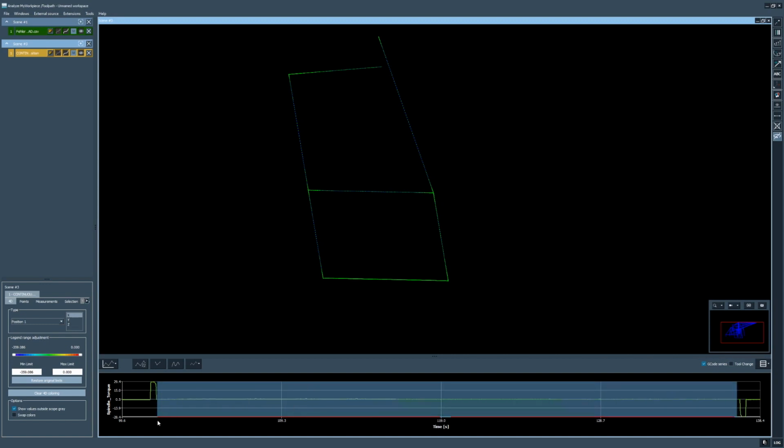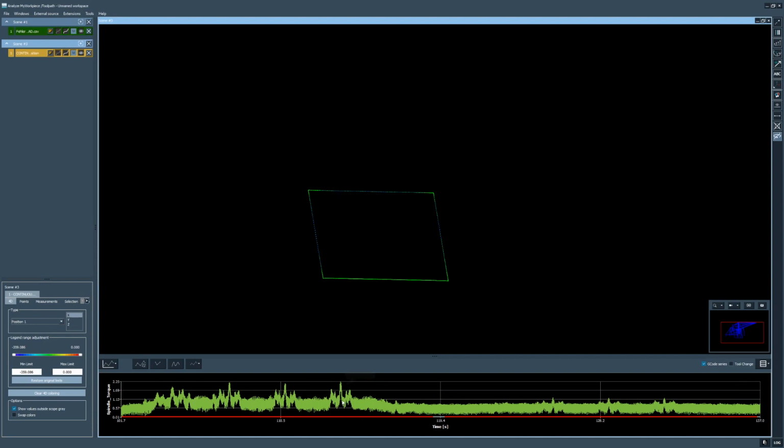So if you want to analyze something very closely and you want to understand where in the workpiece the tool really entered the material, then you want to look for the areas where you only have a non-G0 section.